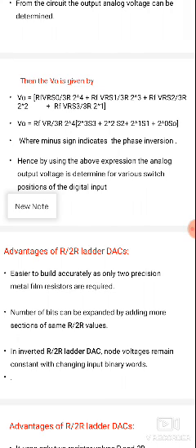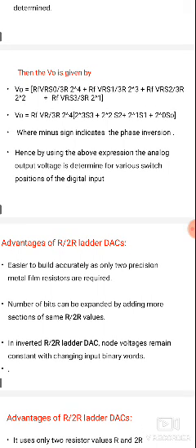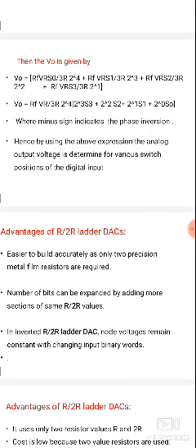First case: RF into VR and switch S0 by 3R into 2 power 4, plus whenever S1 is 1, RF into VR S1 by 3R into 2 cube, plus whenever switch 2 is 1, RF into VR S2 by 3R into 2 square, plus whenever the MSB bit is 1, RF into VR S3 by 3R into 2 power 1.